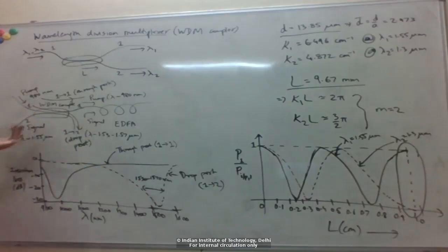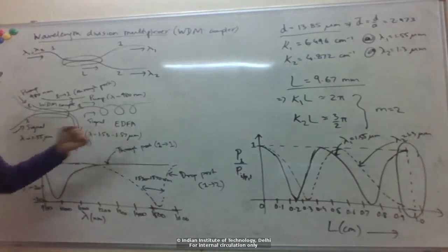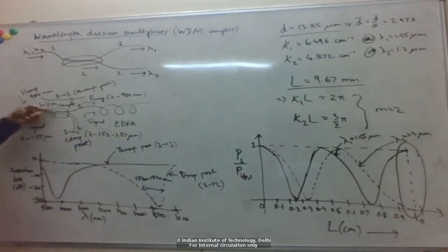But, for example, if you have a coupler which is working for a closer range of wavelengths, for example, these C-L band couplers or splitters. So C band wavelength is basically 1.53 in this range, and then L band is like 1.57 to 1.6, right? So if you want to split and combine those wavelengths, then the fibers will be basically similar. So in that case, the 1 to 2 and 2 to 1 both will have the same response. But typically, when the wavelengths are different, we have designated ports, right?